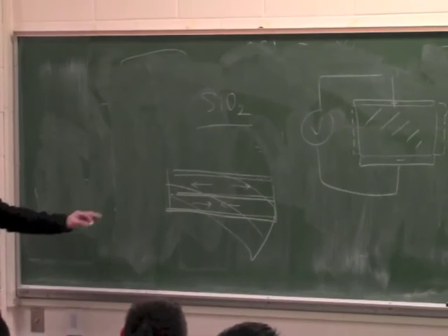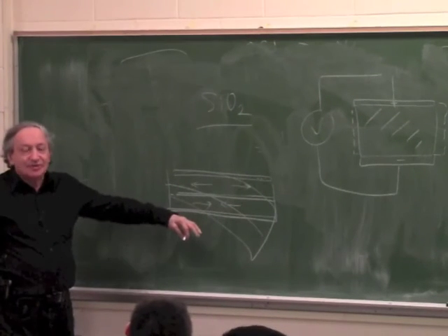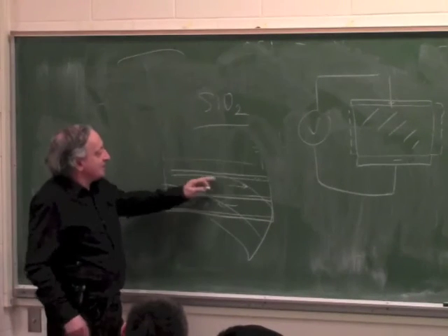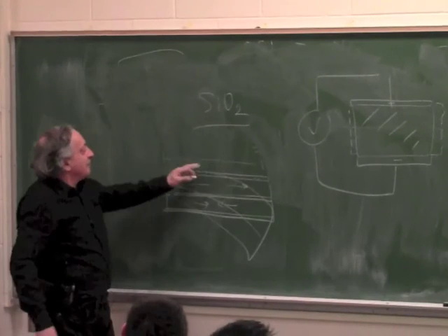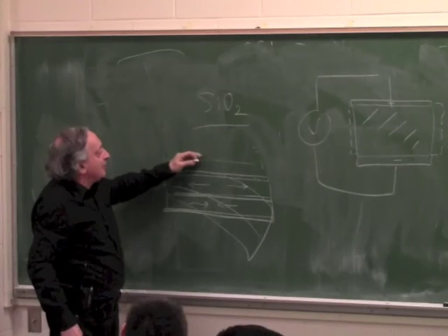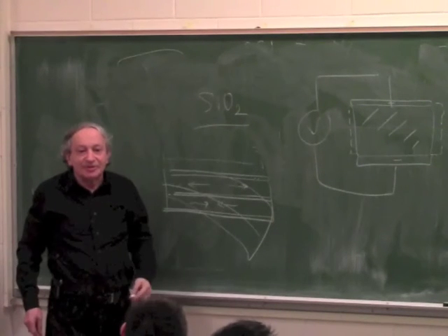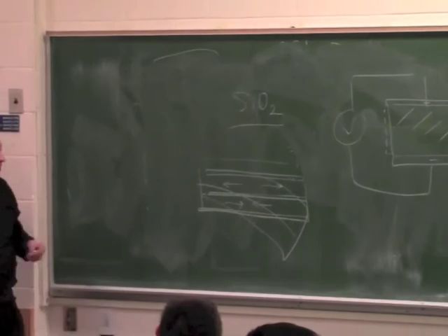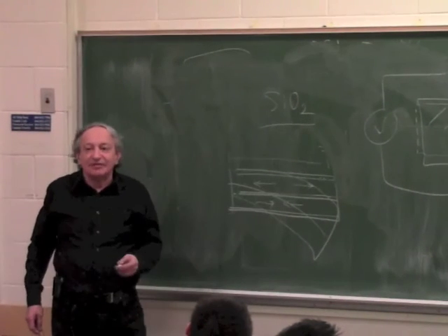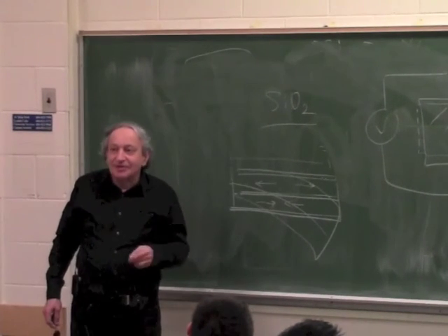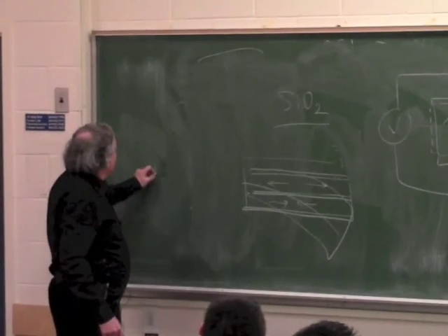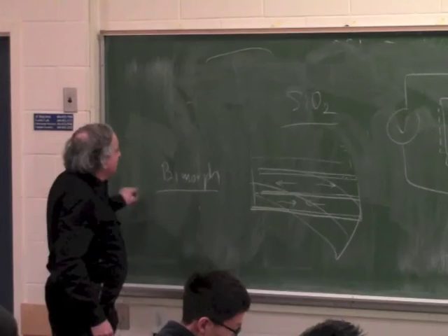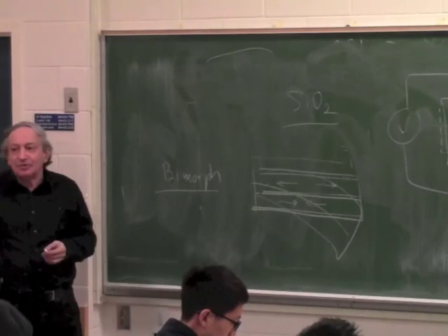Now here you're amplifying the effect a lot, because say that's a centimeter beam, and even if the top is not a millimeter but just a few microns longer, the beam will bend a lot, right? Because it's a huge magnifier. If the beam has 0 thickness, the magnifier is infinity. So this is called a bimorph, and it is used a lot when you want to amplify the piezo motion.